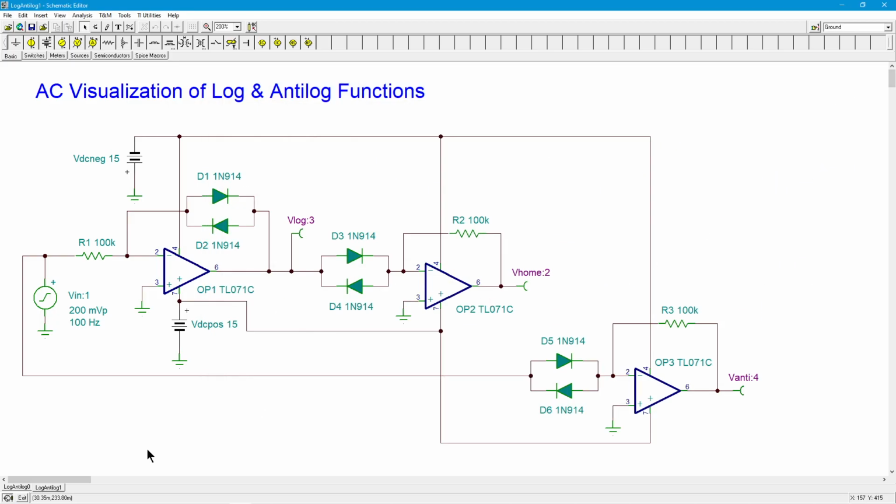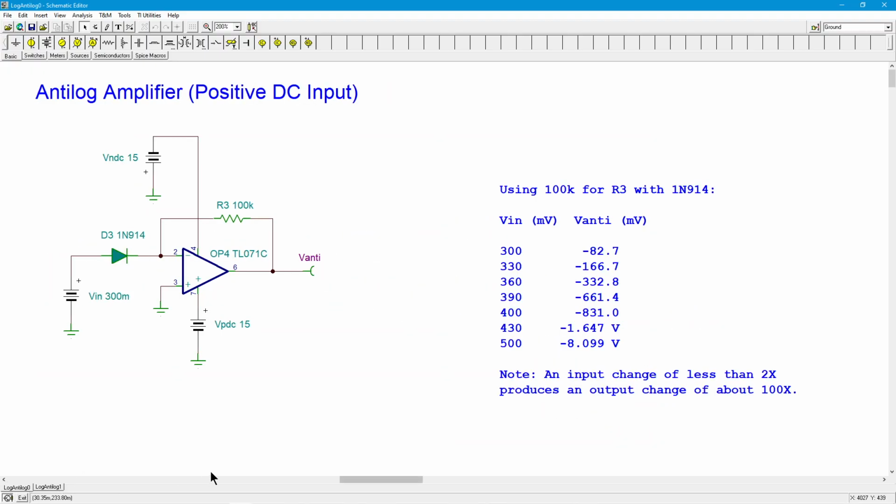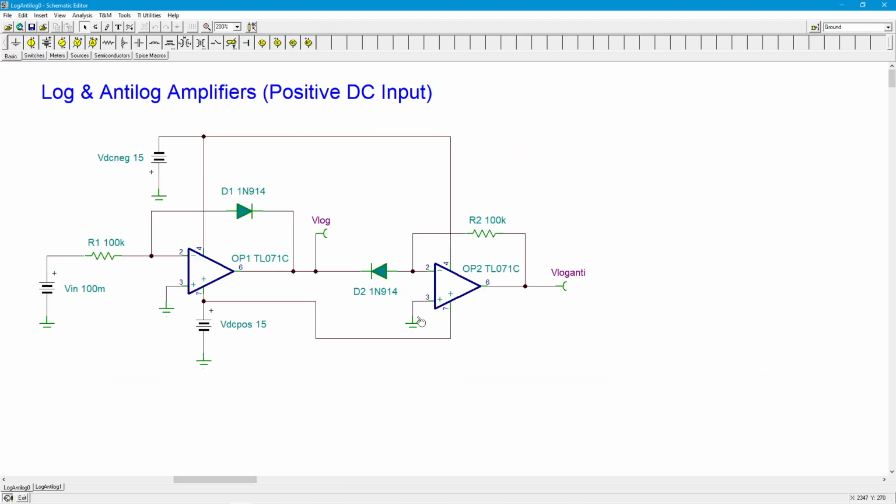All right, so we have these basic log and anti-log amplifiers. They can get much, much fancier than this. Like I said, there are some issues with these by themselves. Temperature is a notable limitation, but this is a nice introduction. You can get the idea of what they're going to be used for, right? So you need to squish down that sensor range, or you need to do the exact opposite, sort of zero in on it, expand it out. These are things you could look for, right? Log and anti-log amplifiers. You can have some fun math with your circuits.